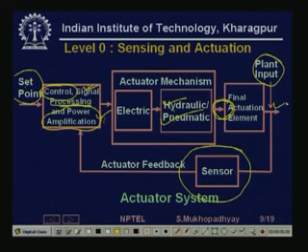Now even that may go through something more. For example, if you have a hydraulic element, what will it finally produce? It will probably be applied to the stem of a valve. So tremendous pressure will be applied to the stem of the valve, but you still have to have the valve because you want to control flow. What you want to control here is flow, let us say. For controlling that you need to move a valve. This is the final actual element. So you have a control valve.